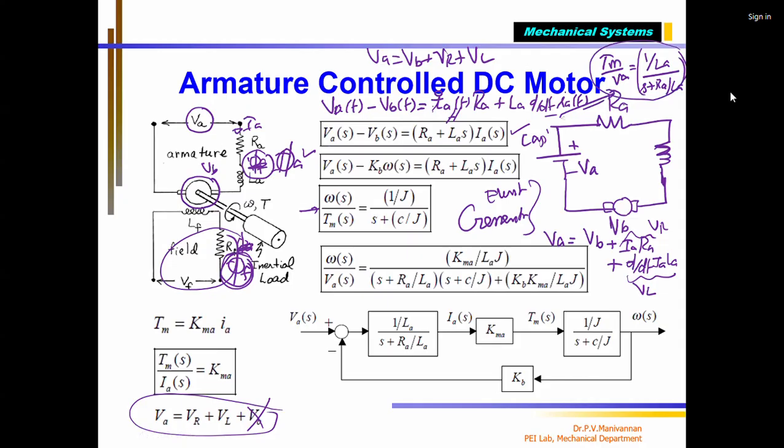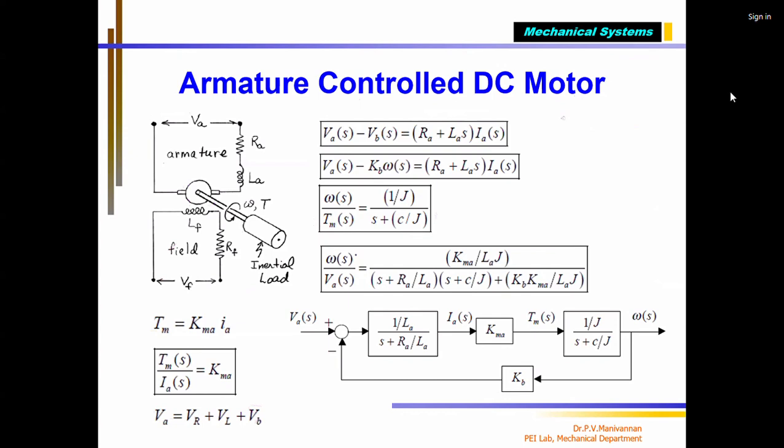Then this torque is given to the mechanical part. For the mechanical transfer, we already saw the same thing, whatever we saw here. So the final transfer function, I just wanted to clear everything, is nothing but the angular velocity of the armature, which is the shaft speed, with input VA. If I vary VA, we finally get the equation. This can be represented as this block diagram. I'll stop here. Tomorrow we have class 5 to 7. I will be taking it for 2 hours. I told you, because we wanted to complete some syllabus before our midsem exam.